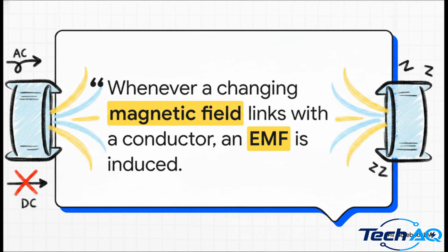Now, I want to really focus on that word changing. A transformer only works with alternating current, or AC. If you were to push a steady, unchanging direct current through it, absolutely nothing happens across that gap. The magnetic field must constantly be shifting, expanding, and collapsing to actually push the electricity across our invisible bridge.